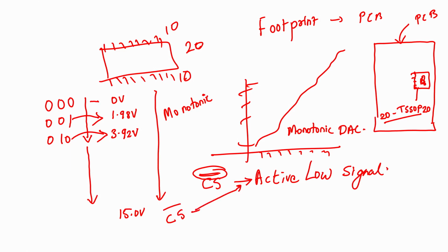Active low means that the signal, or the functionality of the pin, will be enabled when the value of the signal is 0, so that the complement of it, which is what the bar does, becomes 1 and it becomes high. So, that is active low. Active low means that the signal or that pin is active when it is low or 0. So, this you should understand.